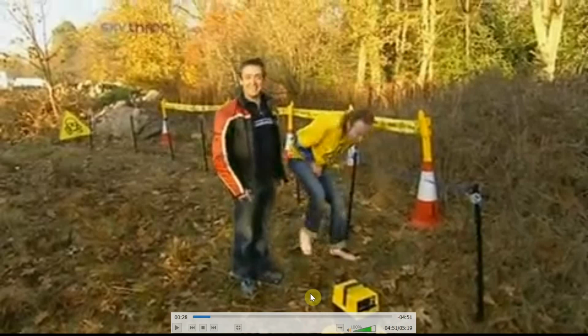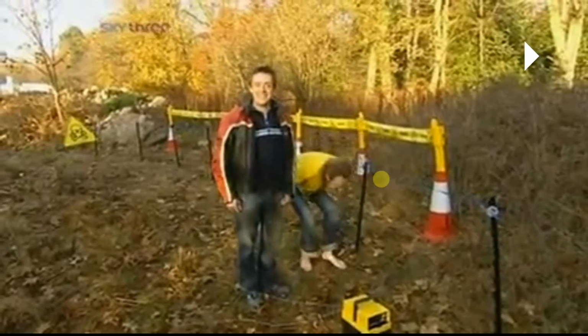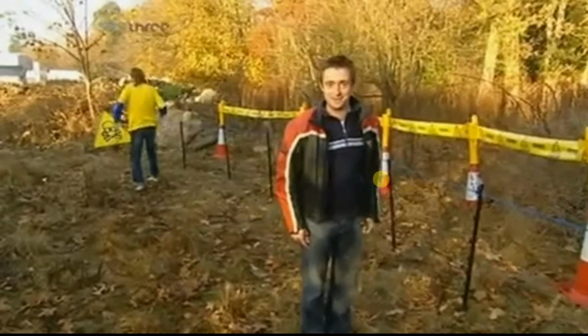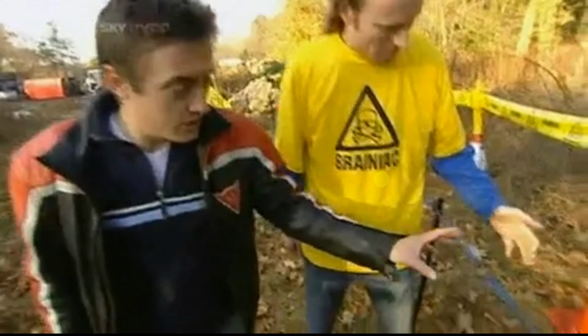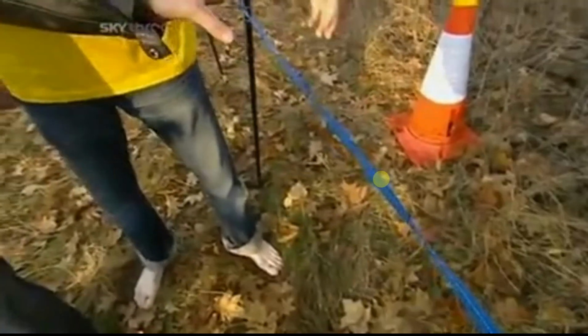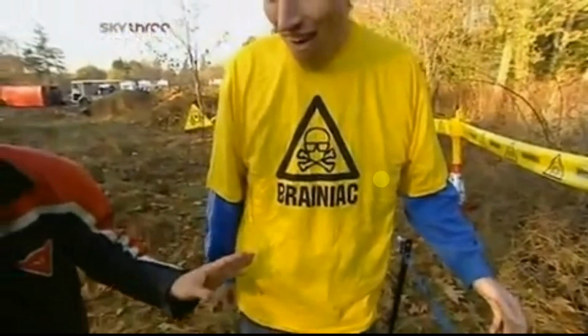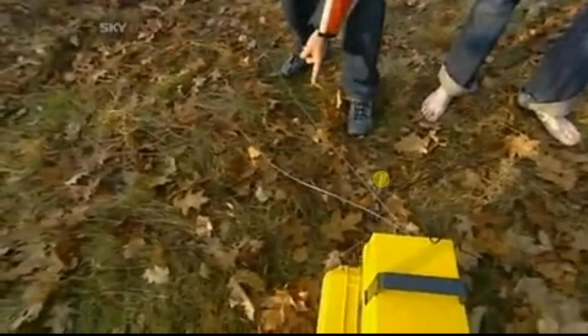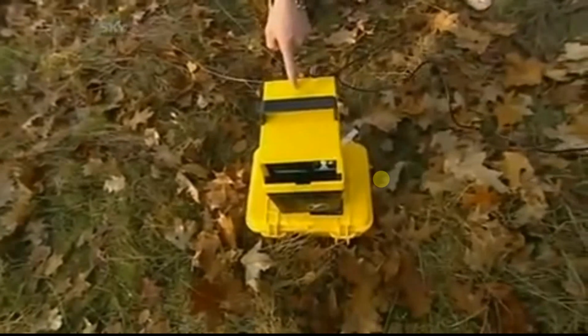Look, see these two very thin wires? Those are the wires plugged into the earth, back into the electric fence device, back up through the electric fence. There's the completed circuit. This happens because when he touches the fence, it completes the circuit between the live wire and the ground. The charge goes from the fence itself into the brainiac's body and down into the ground. Then it goes along the ground into the earth stakes, along the earth wires,